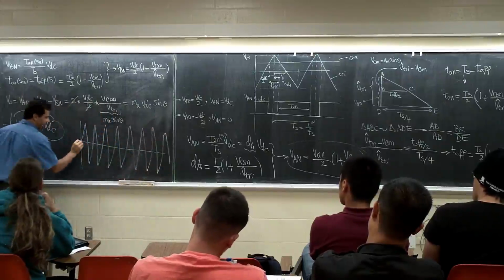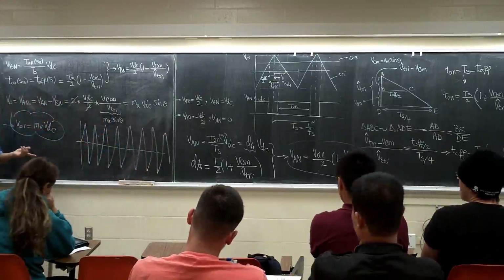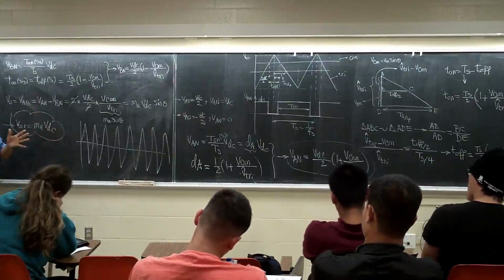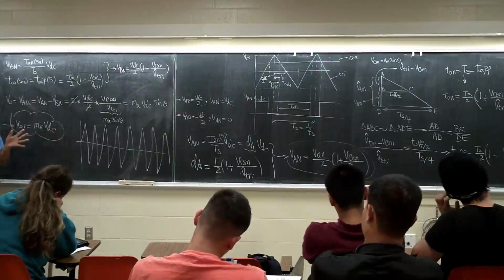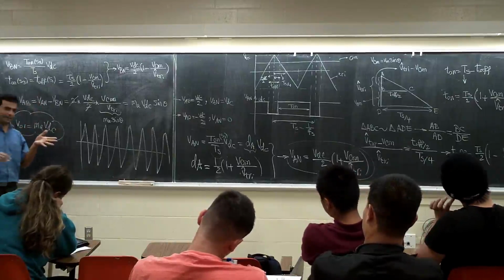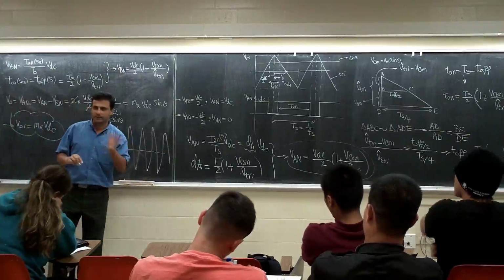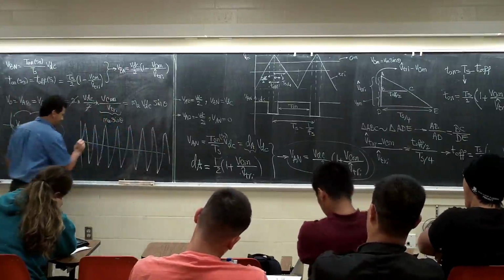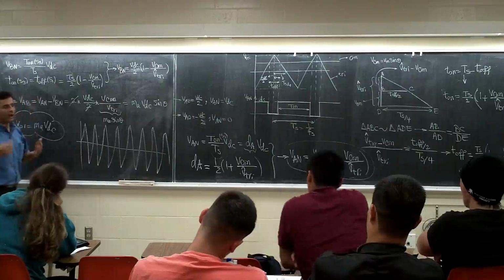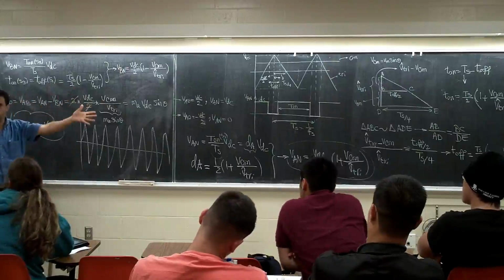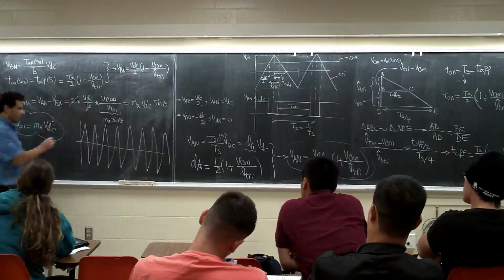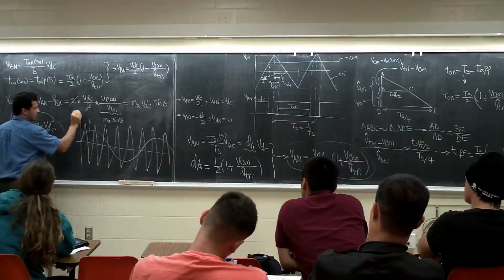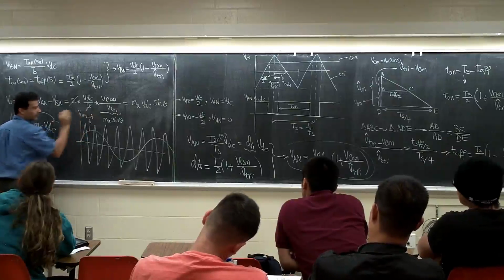Now, for phase A, if you go back to the energy conversion or the first class of the power electronics 1, we said in a balanced 3-phase system, phase A is at 0 degree, phase B is at minus 120 degree, phase C is at plus 120 degree. And all of them have the same magnitude, right? So basically, I'm going to select my control waveform. I want to have a 3-phase output voltage balanced, right? So I can select this one for my phase A, right? This is the VA control, V con A, right?